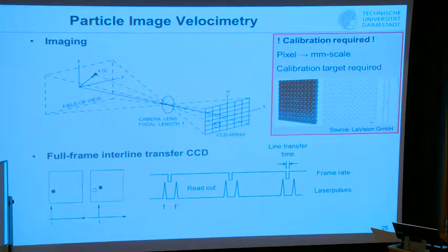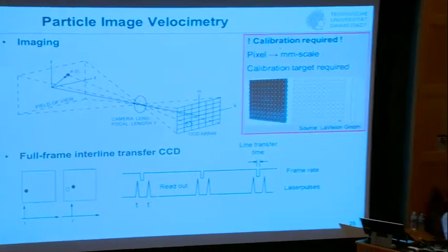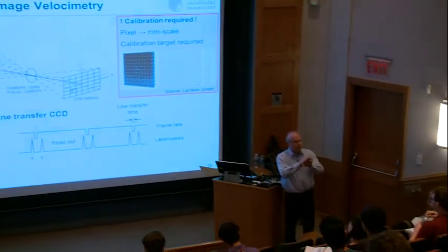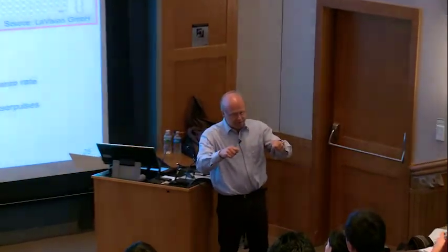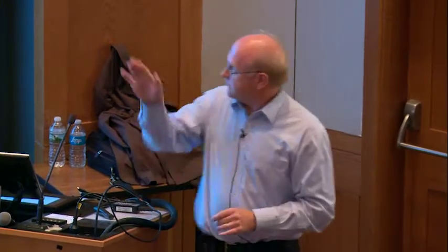So at least one company came up with this so-called self-calibration and extended that to volume self-calibration. And the idea there is that based on this initial guess of this mapping, you take the particles themselves, let's say from the first exposure, to check whether these particles are at the corresponding positions on the cameras. And there might be still a small shift based on this calibration target, because you have information only at these dots, and in between you do an interpolation maybe with a third order or something like that. There still is room for, let's say, errors, and as well these dots are rather large. If you take the particles themselves, you can do better.